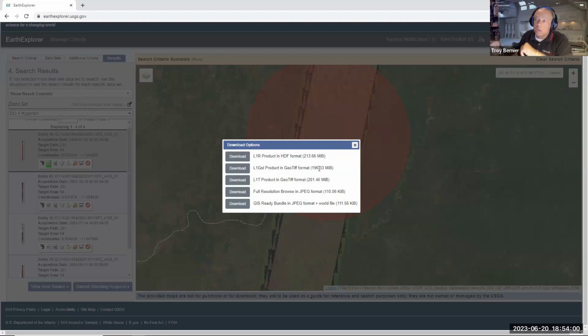Depending on the tools that you use, if you're using QGIS, you're going to be maybe looking at this one. If you want to use this one in QGIS, you're going to have to break those bands down so you can use them as individual bands, and then create a virtual band or do whatever band map that you might want to perform.